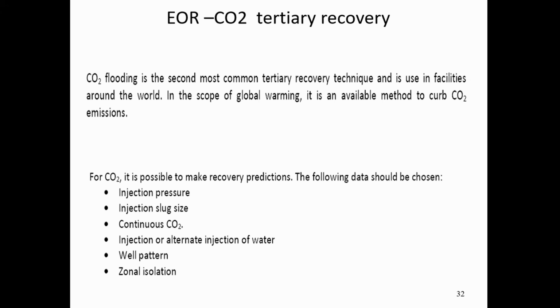Shall we do injection? No, I prefer to do flooding. I flood it inside the oil reservoir. I don't inject the CO2 gas inside the gas cap. It will reduce the heating value of the gas cap.